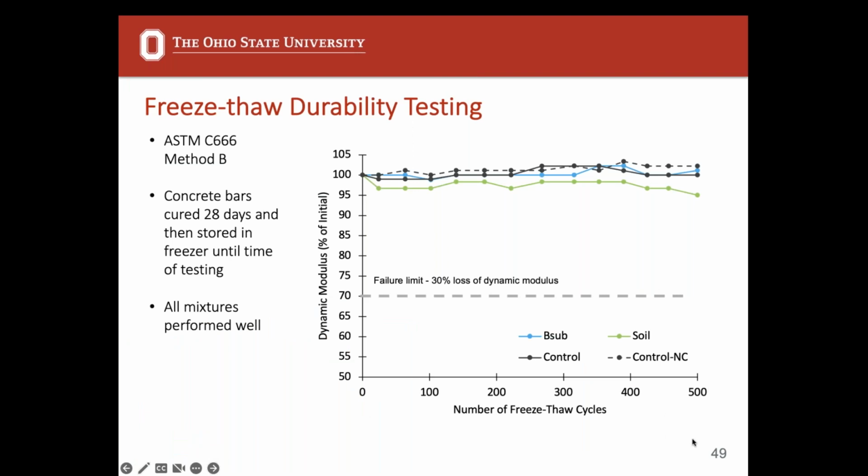Okay. We also, as part of the concrete testing, performed freeze-thaw durability testing. We wanted to see if the densification of the concrete would reduce overall freeze-thaw damage in samples. And unfortunately, we cast a QA or QC1 ODOT mixture, and it looks like that mixture is really high quality and does really well in freeze-thaw durability testing. So that's great. Yay, our standard mix works. We were not really able to tell a big difference between the bacteria samples and the control samples, though.